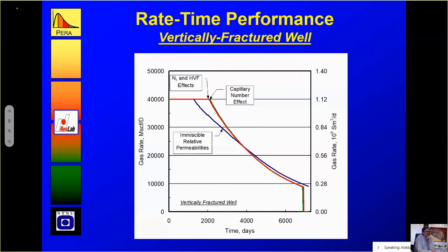So the reason we are asking is that we were writing a paper about it and we saw that there is actually an effect of condensate blockage in vertical fractures. Because our initial thought was that it also is infinite conductivity, there is no pressure drop within the fracture. But when we compare it with the real data, we see that the fractures are not really working as ideal.